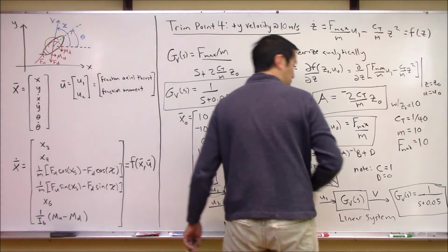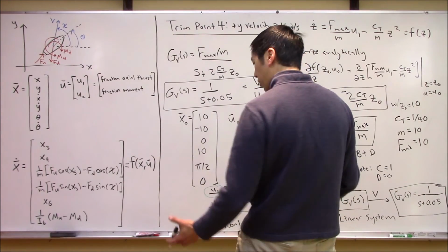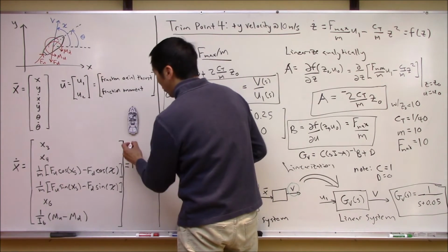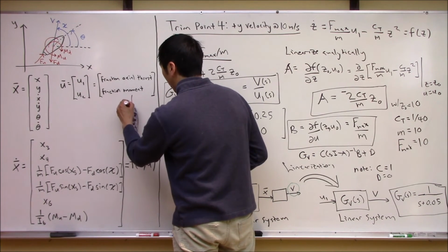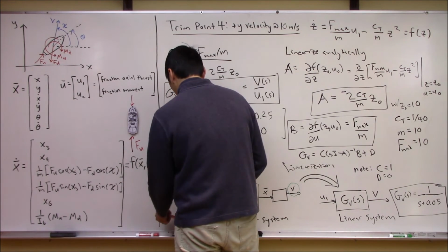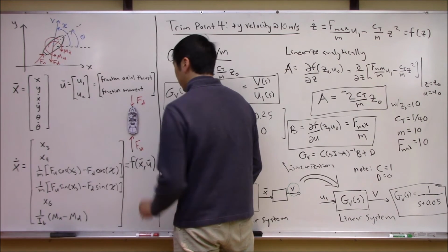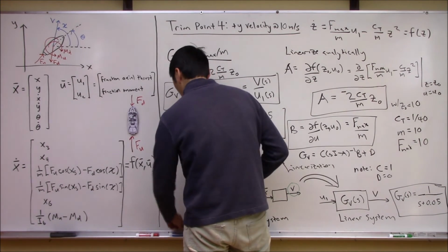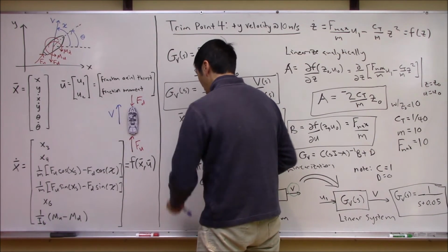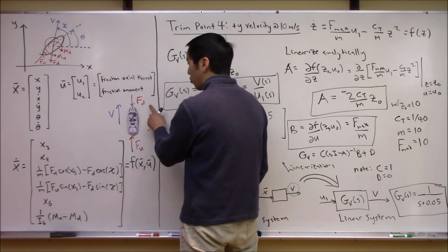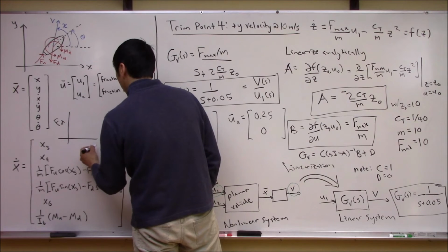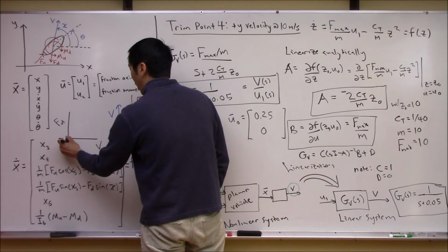We talked about this earlier, the picture that went along with it, or where did my little boat go? Oh, here's my vehicle, right? When it was going straight, we had the situation that at trim, the force from the axial control is going to have to equal the drag force, right? When this boat was moving at some sort of velocity v, right? So what's coming into play here is that this drag force is nonlinear. If we were to plot F drag versus velocity, I think we're using a square function, a quadratic.